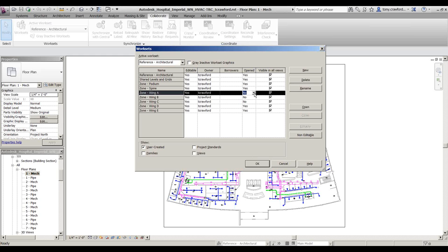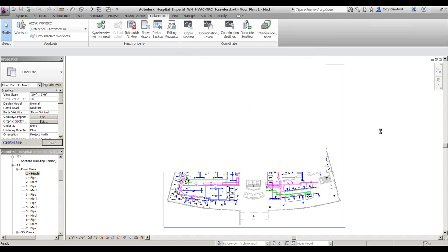So that's a good place to be. And I agree, this is one of the best tips you can use for speeding things up a little bit. Yeah, and these are, well, sort of in order, but not completely. So that's what I would start off with. Like I had the RAM up there first, closing worksets, unloading files. Those are quick and easy to do.